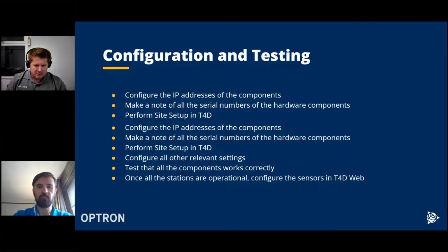So what we tend to do is we do the initial setup and then we remeasure all the orientation so that from the start all the orientation and the total station position fits well together within this, let's call it, the localized monitoring network. Cool.